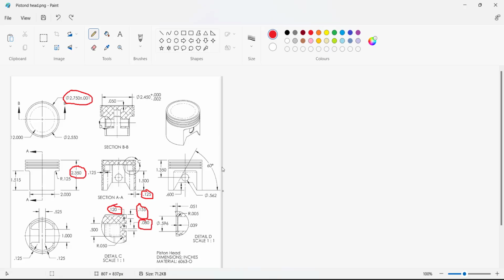Okay, so if you see in the drawing, the distance between these two tabs is given as 0.12 for all the tabs, and the distance between the cuts is given as 0.08, and for the first tab it's given as 0.155. So that's why you have to try to understand this one. He does not give the dimension for all of these tabs. He just gives the dimension for one tab and one cut.